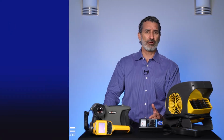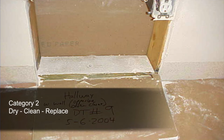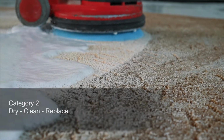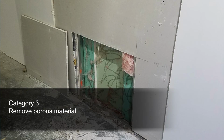With Category 1 water, you have the option to dry building materials in place. With Category 2 water, you're on the fence. Depending upon the material, you may replace or clean. With Category 3 water, you're going to remove materials, particularly porous materials that are affected by Category 3 water, such as carpet, drywall, insulation, etc.